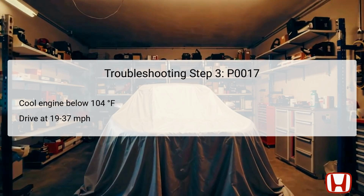This range is pivotal as it allows the vehicle to operate under normal conditions where the VTC system should ideally stabilize. It is important to monitor the HDS for the EXVTC status indicator to ensure it turns on during this driving phase. If the EXVTC status does not engage as expected, it may indicate a persistent issue within the VTC system or timing components, which should be investigated further. By observing these parameters, a clear understanding of whether the issue has been resolved can be established.